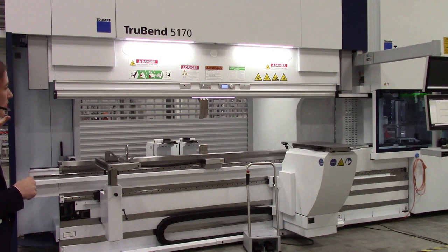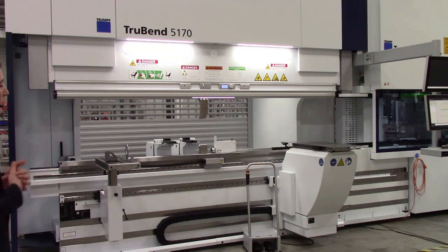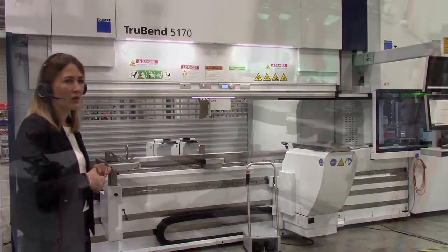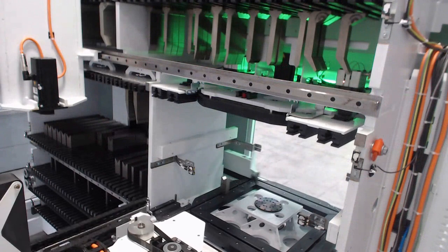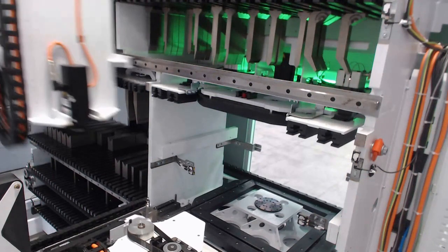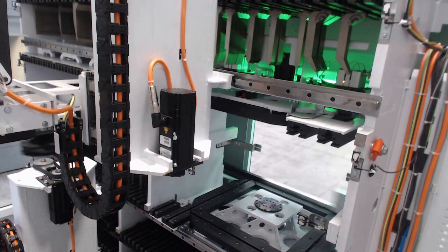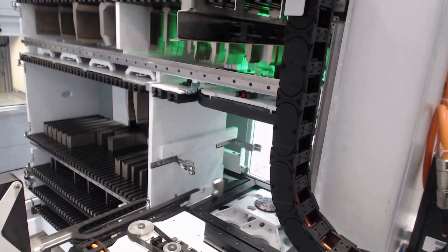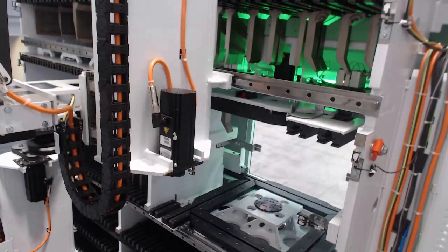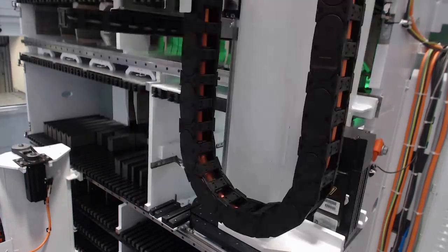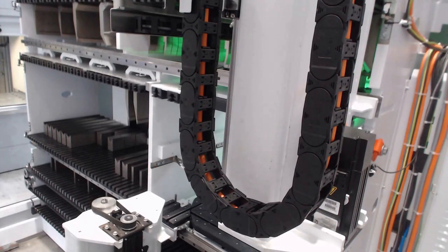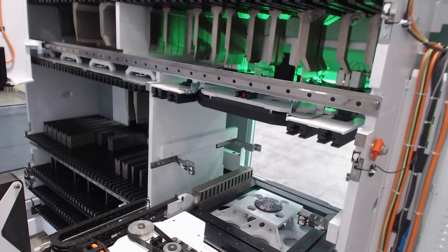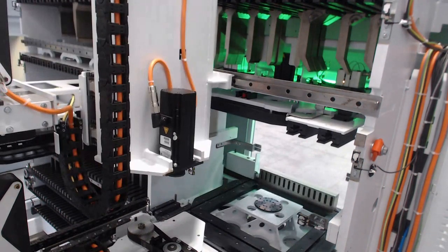The tool shuttles will grab the tools and they will put them on a rotating carousel in the Toolmaster. So maybe let's switch the camera view into the Toolmaster. And yes, the shuttles will take the tools and bring them into the Toolmaster, and then we have a rotating table. This is important because, as we saw in the first tool setup, we can use the tools both ways. And so the Toolmaster will automatically rotate the parts as we need them for the program. So after the tool shuttles pick up the tools and put them on the carousel, there are two manipulators at the back that will pick up the tools and store them where we need them.